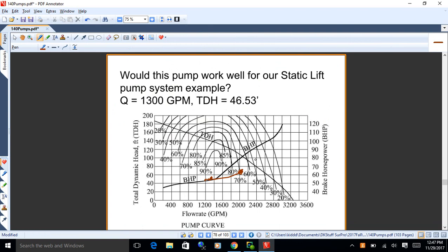Yeah, we're a little high now, aren't we? Which is what we want, because, I'm sorry, no, I've got the wrong side here. Here we go. Yeah, we're right about on it. Okay, so that's pretty good. I think that thing's going to run at about 2,400 gallons per minute. That's what it's going to do. So the pump will just keep running until it hits the pump curve. That's the idea.